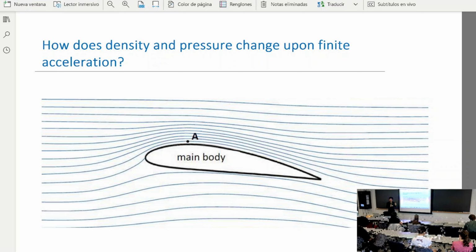That's for low subsonic flow, Mach number close to 0. When you get to higher Mach number subsonic flows, the same contraction drives more pressure coefficient change, with a factor of 1 over 1 minus M squared. Then when you get to supersonic flows, the relationship becomes the opposite. Upon the contraction of the flow, the pressure coefficient actually increases, not decreases. So that's what we discovered last time.